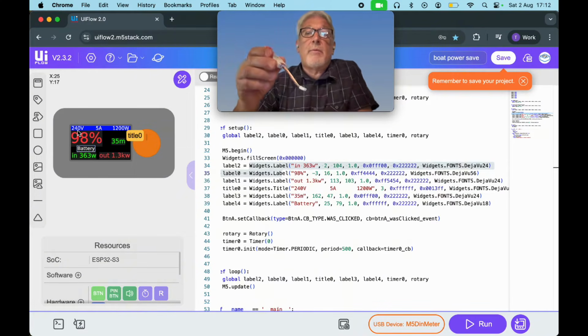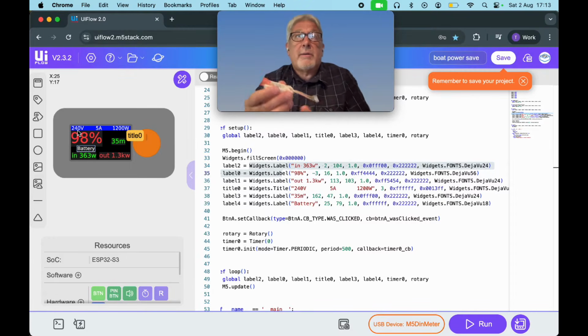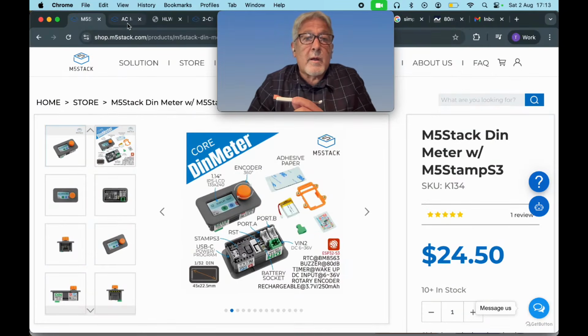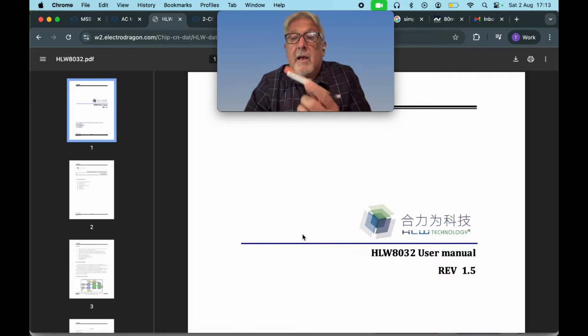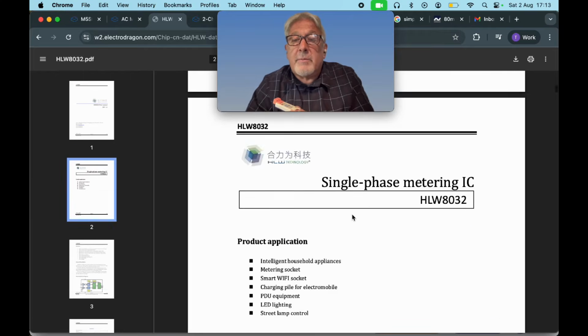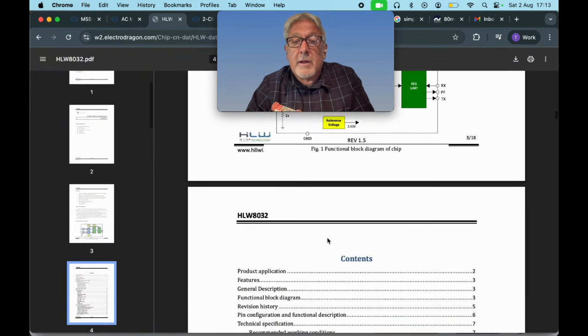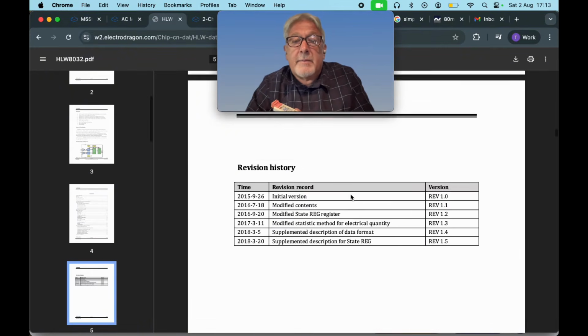And there's going to be one of these behind each plug in the boat, and then those are going to be aggregated by the Raspberry Pi, so I know how much power is being used. So this uses this chip, which is a HLW8032, and that chip is designed for metering. It's a tiny little chip that has all the pieces in it to meter AC power.